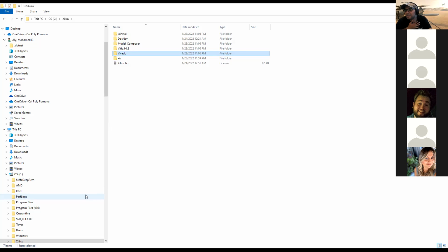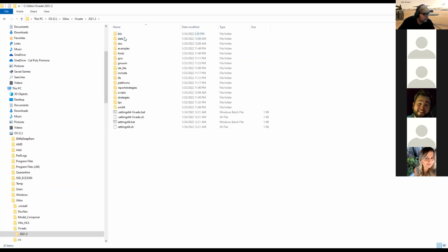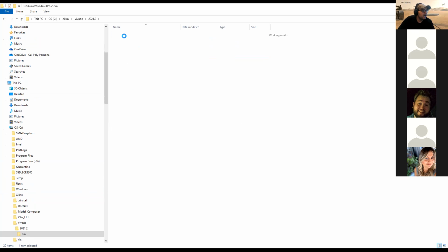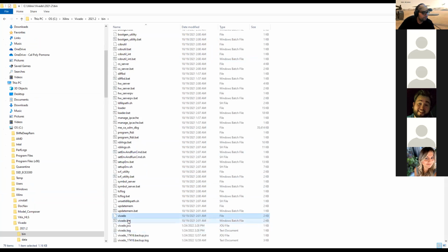I found something on the internet that helped me solve this problem because it's a Java problem. I went inside here, Vivado, and I go inside 2020.2, and I go inside bin, and then I search for what? Vivado.bat. I click on it, it opens. And if you look, it opens.